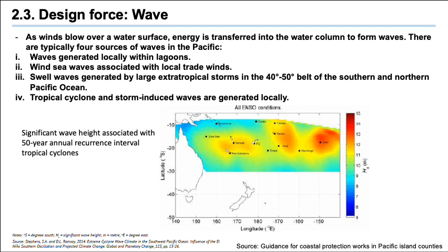The actual wave height reaching a particular coastline is highly affected by local bathymetry and presence of offshore fringing reefs, which cause breaking and refraction of incoming wave energy. Local nearshore wave modeling is typically required to resolve nearshore wave processes.